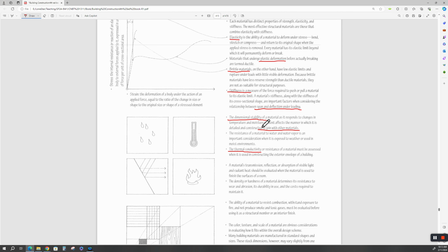Because of the moisture content. The waterborne salts that they used to treat that lumber were being sucked out by the hot sun. So I built me a cross jack and pushed that stuff down flat, welded the front toe plate, moved the jack to the back, jacked the boards in place, welded the back toe plate, and